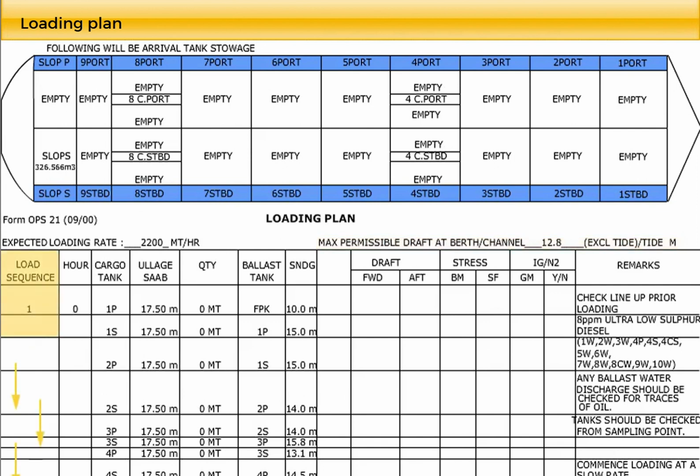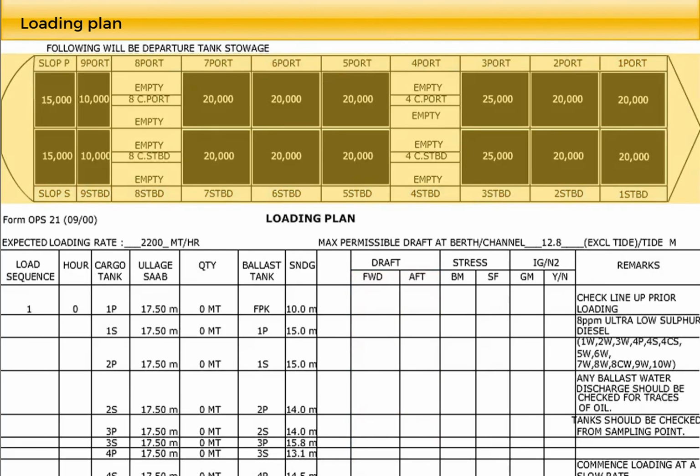Throughout the operation, the indicated tank ullages help junior officers and the pumpman to know when a certain stage of the loading is reached, and the next steps should be taken. Comparing visual drafts with those shown in the plan helps the officers in ensuring that the loading is going safely according to the plan. The plan also shows cargo specifications and a tank diagram spreadsheet with details on cargo grades, quantity, and their distribution into different cargo tanks.